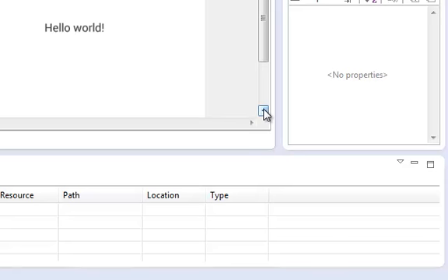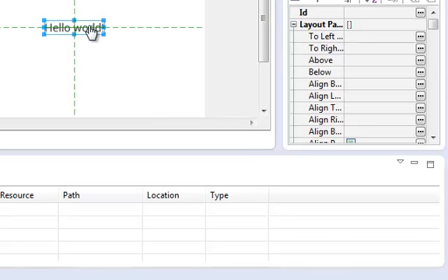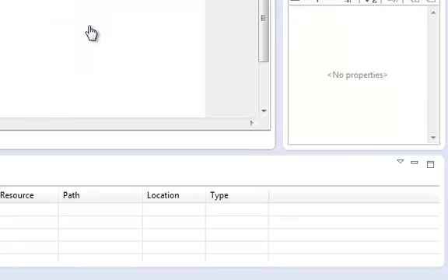Just to get some functionality in how this package works, you're going to click on Hello World, which is indicated in your directions on step number 2, I believe it is, on page 16. You just click on that with your mouse and then just press your delete key on your keyboard. And the little green arrows indicate that it's centered in the middle of your particular emulator or cell phone simulator. Click delete and this will go away. That takes care of that part.